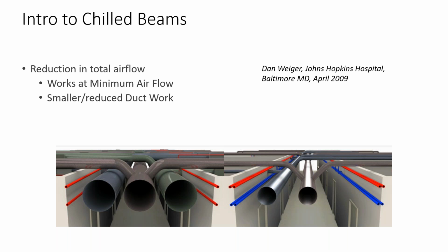And then we added in chilled water, but notice that there's only 2 duct runs. And that is because you have basically just a supply and exhaust into the space. For chilled beams, you don't have a return because we're not circulating air back to a top mechanical unit, and then we add in the chilled water supply that goes to the beams.